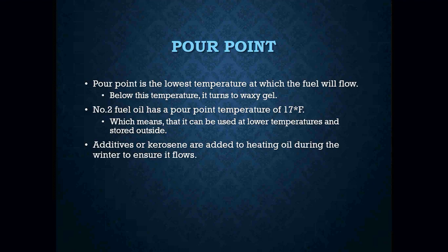A successful fuel treatment program requires knowledge of the quality of the fuel in the tank and the specific service problems. Using additives off the shelf without testing may be more harmful than doing nothing at all. So you've got to really do some research if you're going to add some sort of additive to an oil, if you're having a lot of pour point issues or flow issues.